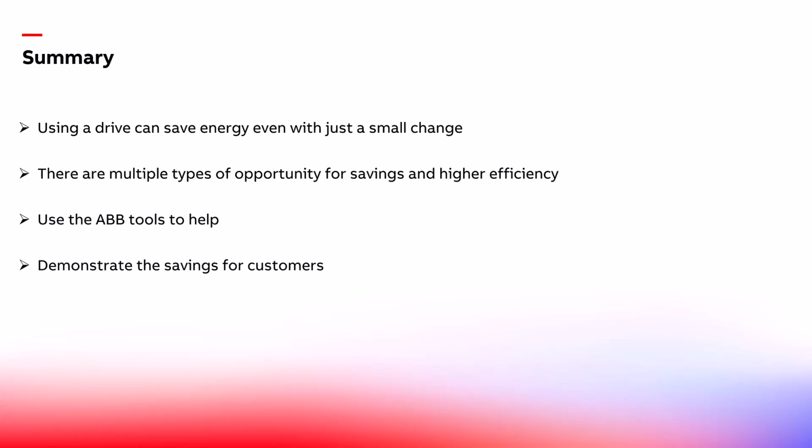As we've seen in the earlier slides, just a 3.5 hertz reduction, 7.7% reduction in speed basically, can save up to 20% of the energy, which is quite a lot. I think such a small reduction in speed wouldn't be that noticeable, and we've seen applications before where people have reduced it by that and they didn't really notice much difference in the performance of the application.